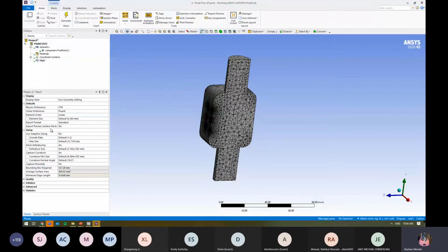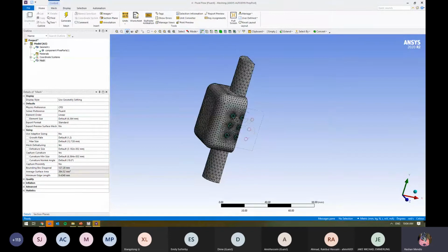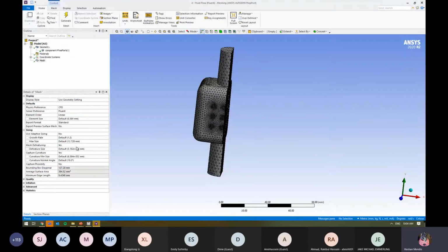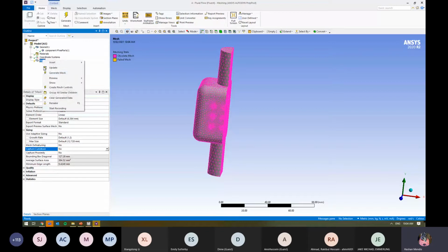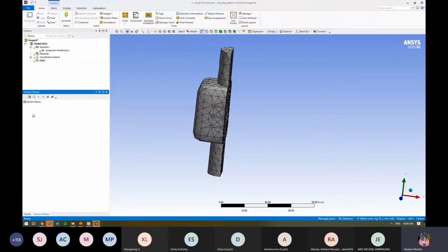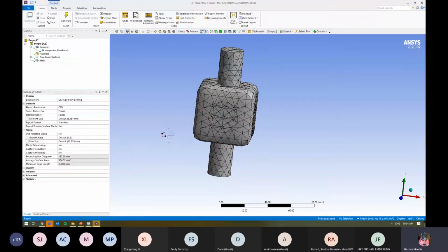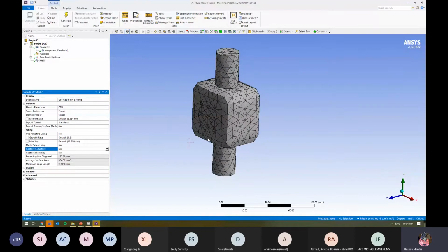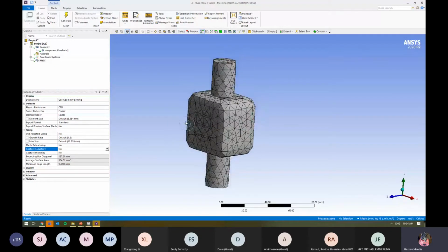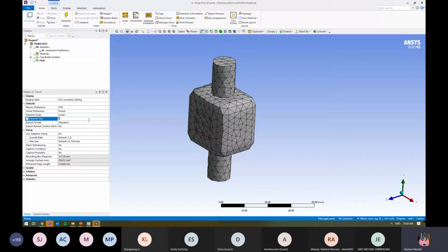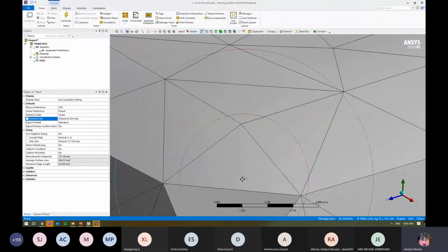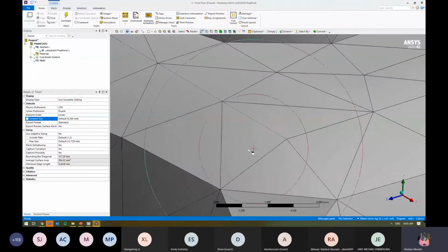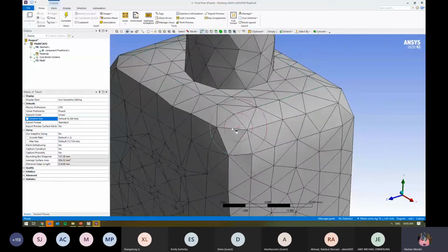You can see here, by applying the general mesh settings, this is exactly what we've got. We can then go in and start to make some changes, right? So let's get rid of mesh defeaturing, and we'll get rid of curvature as well, and then slowly turn some of these things on and see what happens. You'll notice with the capture curvature turned off, the mesh is pretty coarse, and we've got the default element size of around 6 millimeters. We can zoom in, and we've got a little ruler at the bottom to indicate how big something is.